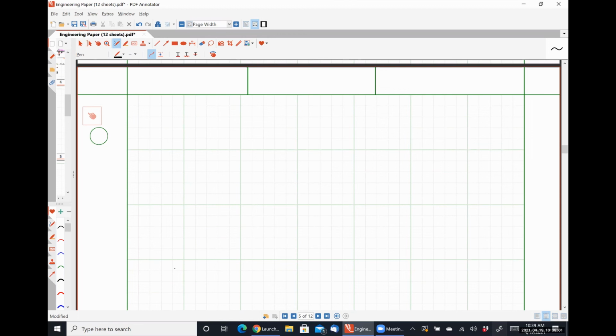So with the source and body tied to the same potential, that's going to look like this. Here is our gate. Here's the source and body connection. This is CGS, making this VGS. This is CGD. Here's gm VGS. Here's r naught.